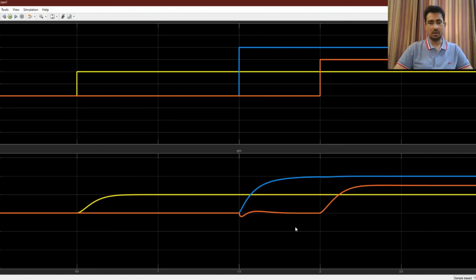You can see that when the second joint starts moving, we have some dynamic effect on the third joint and it oscillates a bit, but then it settles and things get better. So this PID controller is much closer to what happens in real life. But the PD controller was forcing the tuning goal too much by using large gains. So that is not what is desired in real life.